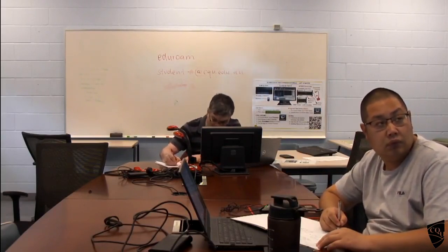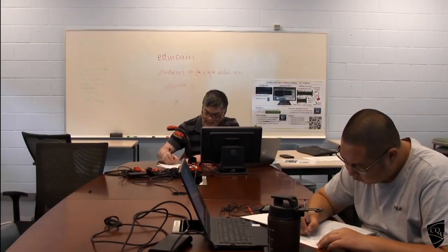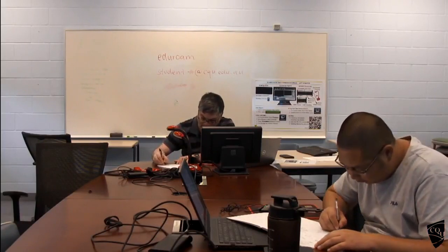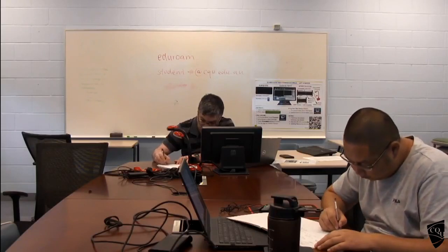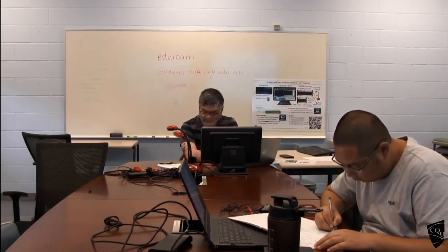This is what I put as y bar, for the uncracked section, UC. So y bar is equal to y bar UC in my tutorial or study guide, which equals sigma A_i y_i divided by sigma A. If you put this in: B D squared by 2 plus (n minus 1) d A_st, divided by B D plus (n minus 1) A_st. This is what is given in the solutions.